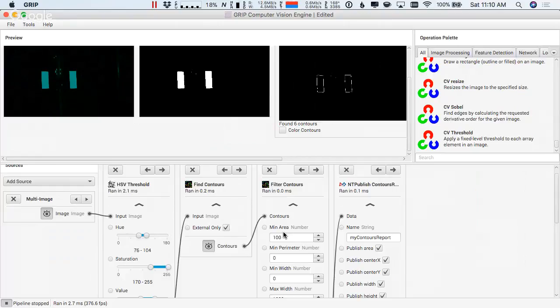Good question. What we found with this is that if the center of gravity is too far off, then instead of moving sideways, it won't do what you expect. There's two things about these that are kind of interesting. One of them is that the CG is off, which is really what causes the problem. The wheels have to turn precisely the amount calculated by the software, and if they don't, then it will not go straight or won't go the way you think it's going. And so on bigger robots, what people often do is they make the frame a little bit flexible so that all four wheels are always on the ground, because if one wheel's off the ground, it's going to mess up its motion.